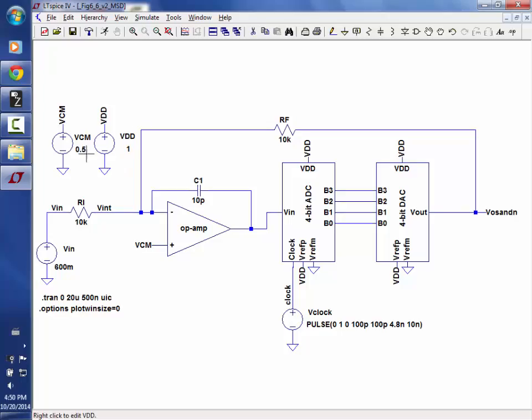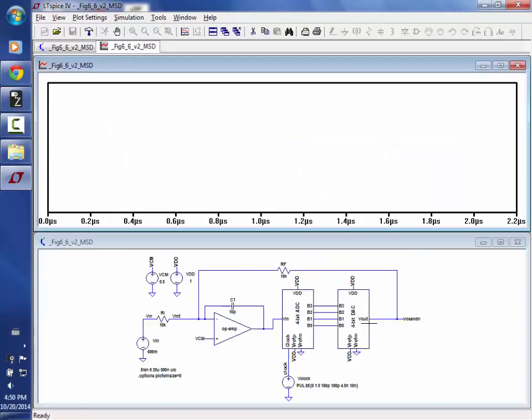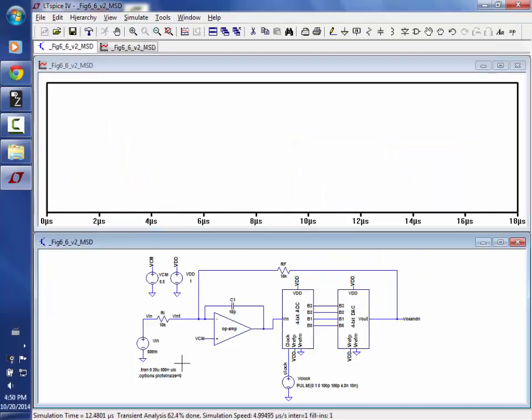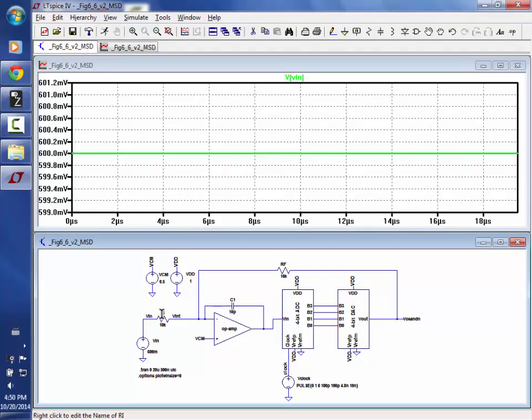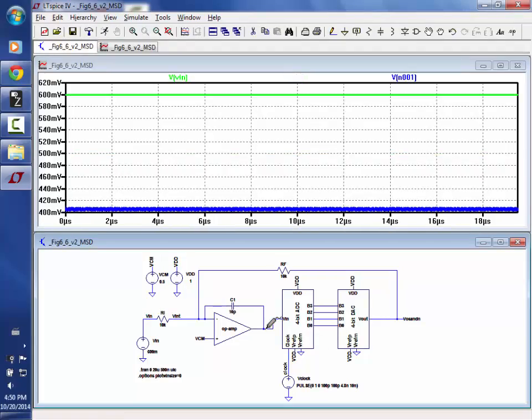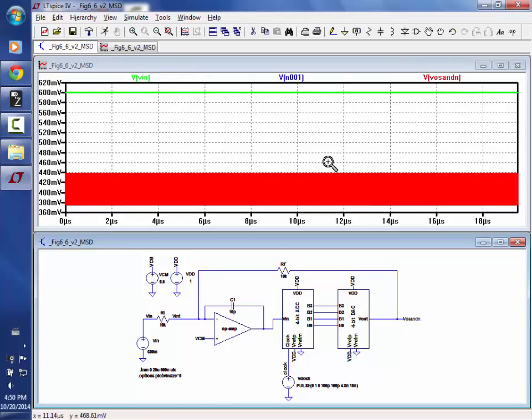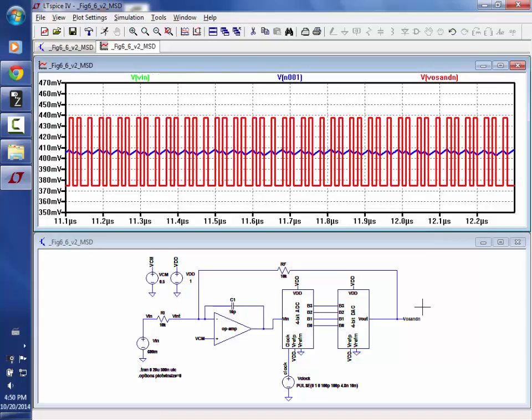So instead of using the capacitor to sum or sigma the currents, here I'm using the integrator, because now this node doesn't change. Then the currents come in here and will cause this to go in the opposite direction. So I hit run, and I'm going to plot the input. Boom. I'm going to plot this terminal, which is moving around. Then I'm going to plot this terminal, which is moving around as well. It should average, and I could put an RC on here, and it should average to 600, minus the inversion. So if it's 600, it should be 400. Does everybody follow that?